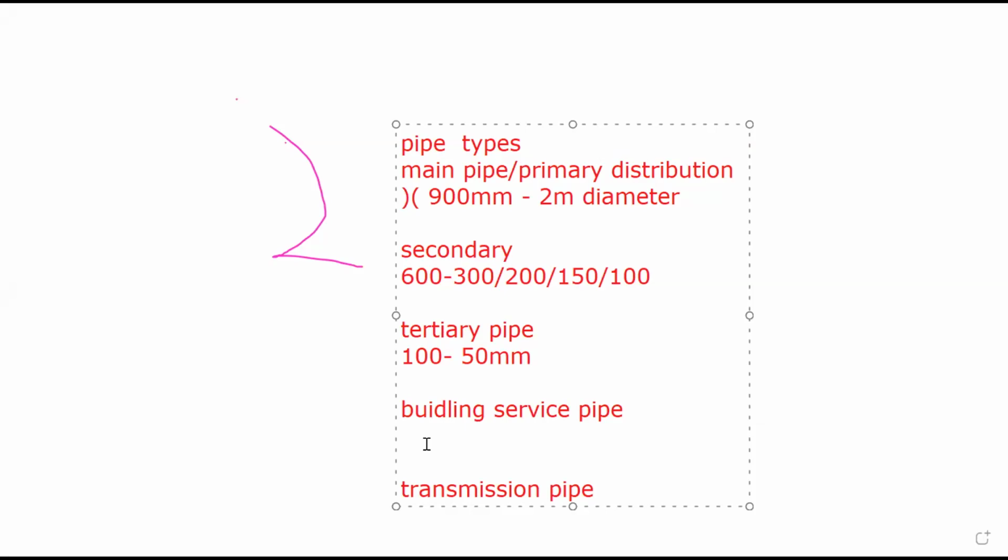But if it stops somewhere along the way, then you know that your rate of extraction is less than the rate of recharge. So you adjust the discharge. But we don't do it here. But that's the way to do it.